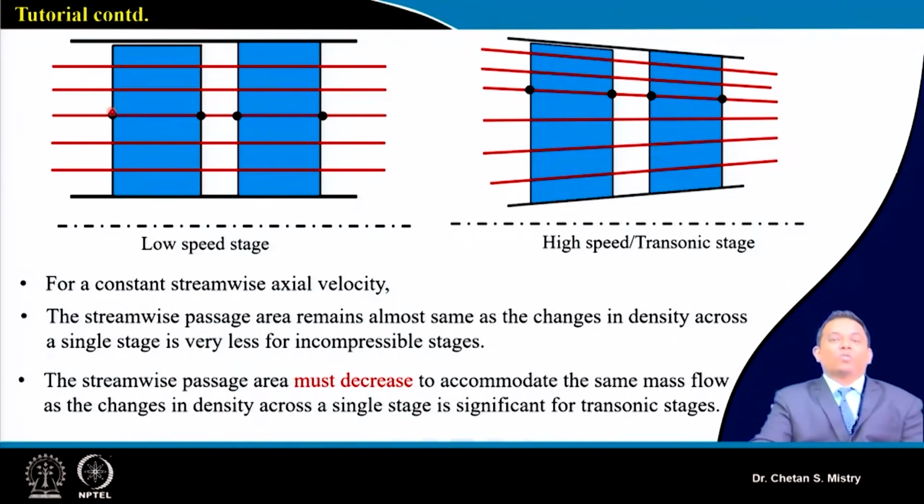Here in this case, what we are discussing is where we say u1 equals u2, but that is not the case here. My entry peripheral speed and my exit peripheral speed are both different. Here in this case, I can say my aerofoil is a two-dimensional aerofoil in a sense. Okay, so this is a flat kind of aerofoil.